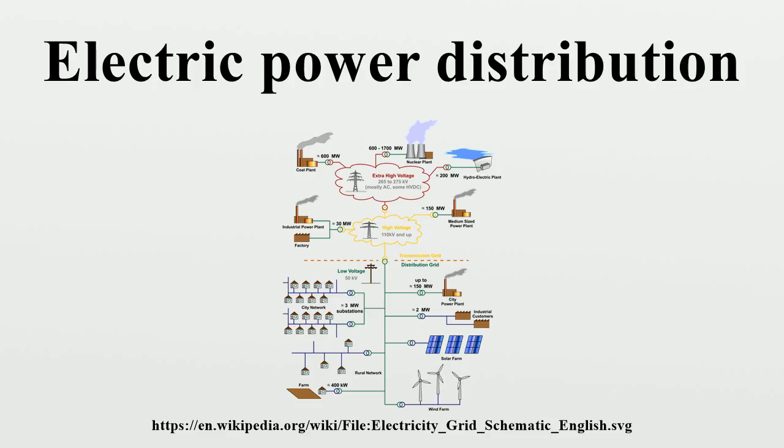Rural services normally try to minimize the number of poles and wires. Single-wire earth return is the least expensive, with 1 wire. It uses higher voltages, which in turn permits use of galvanized steel wire. The strong steel wire allows for less expensive wide pole spacing. Higher voltage split-phase or three-phase service at a higher infrastructure cost provides increased equipment efficiency and lower energy costs for large agricultural facilities, petroleum pumping facilities, or water plants.